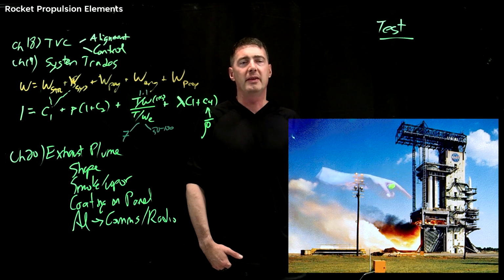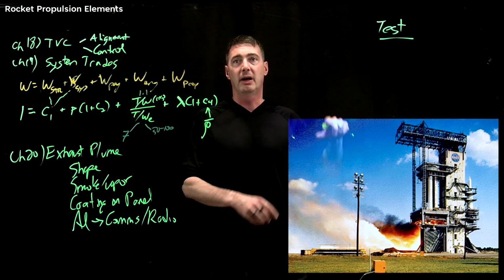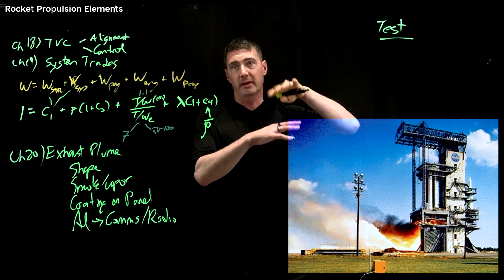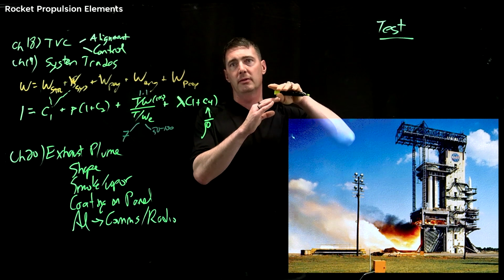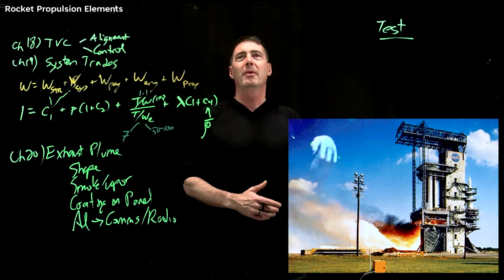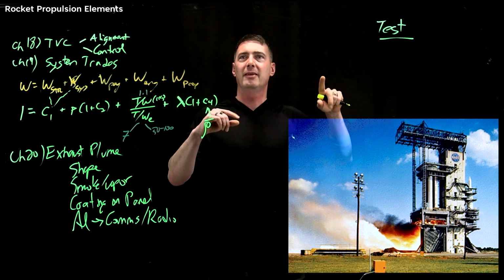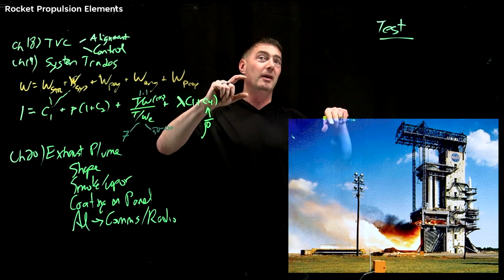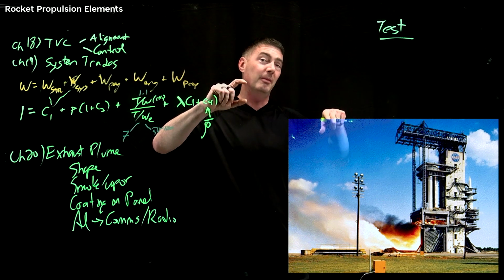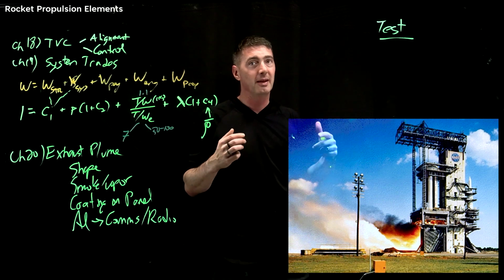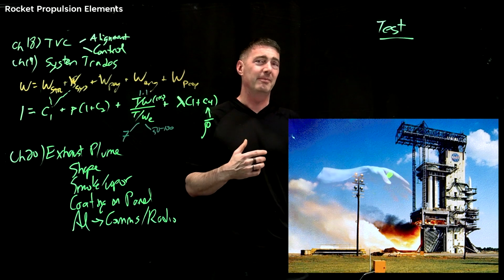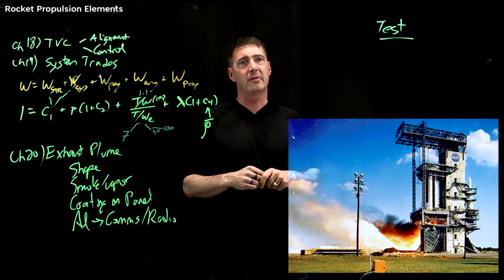A lot of things you may be trying to do here is actually adjust your pressure, sort of backfilling your oxidizer and your fuel, but you're backfilling at a 1G condition, whereas this rocket is going to be flying, starting off accelerating at 1.1 Gs, and then ultimately getting up to 5 or 7. So it's not 1-to-1. Anyway, that's some hard systems analysis there.